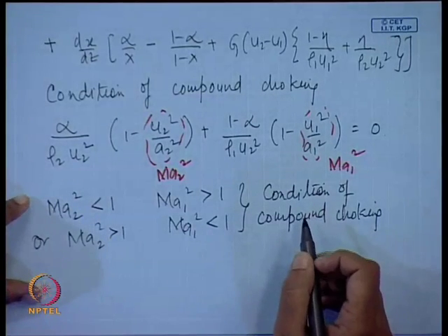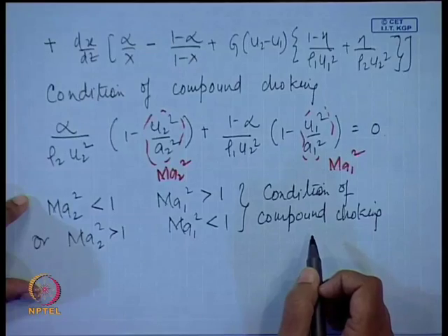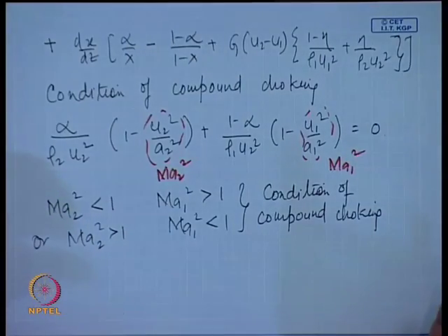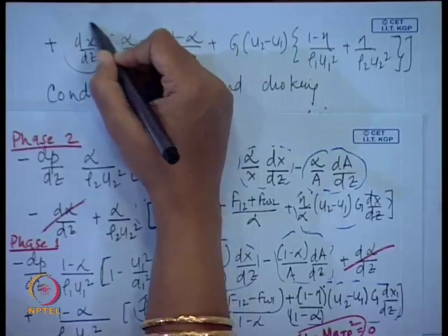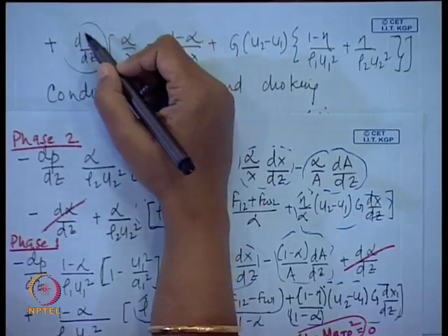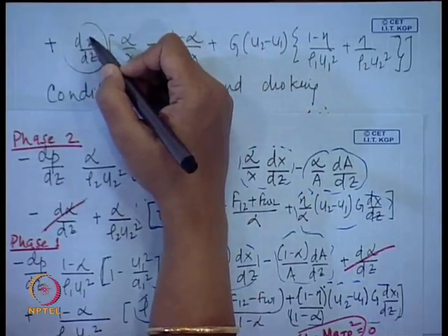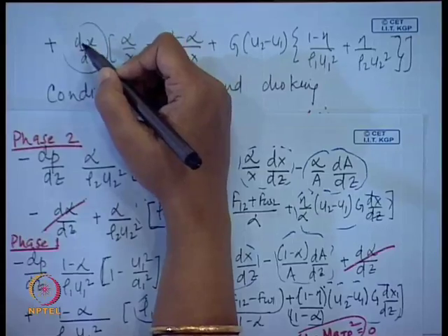But provided, what are the things that we have assumed here? Again, neglecting flashing, number 1, and number 2, if you notice this equation, you are going to find out. First thing is, I have neglected the dx dz terms. I have assumed dx dz to be constant. Okay? For flashing, again in the same way, this x will be a function of h and p. This is the first assumption.